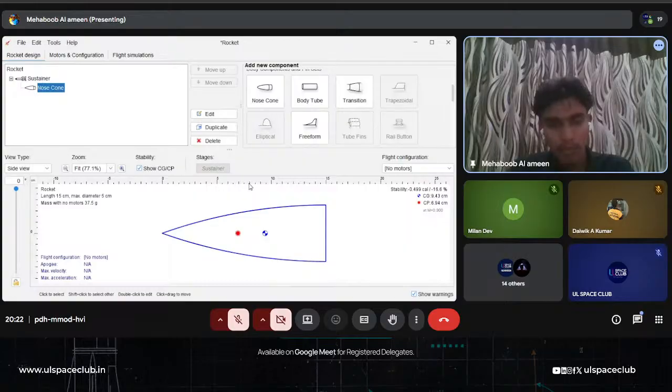When we smoothen the product more, especially the nose cone structures, it creates a lot less resistance to the airflow, which will substantially increase the aerodynamic performance. So we had to select what type of finish the product has. I'm just going with the regular paint, 60 micrometers. Okay.